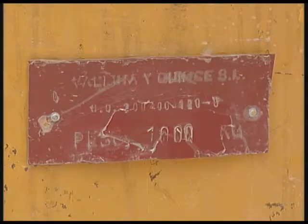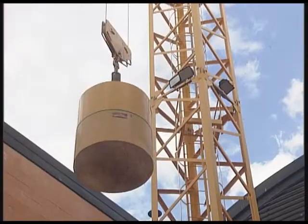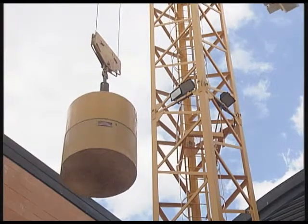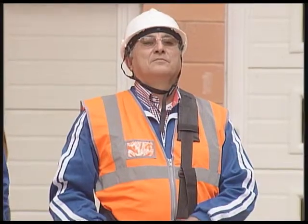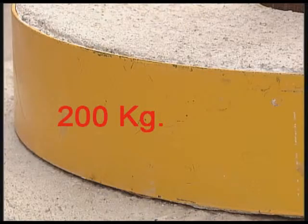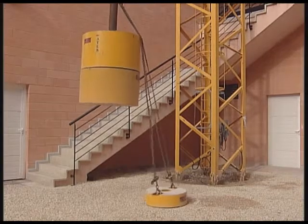Maximum load. Using available materials at the construction site, the crane is loaded with its nominal maximum load. It should be capable of lifting this load. The load is then increased by 10%, thus overloading the maximum nominal load. The crane should not be able to move the load.